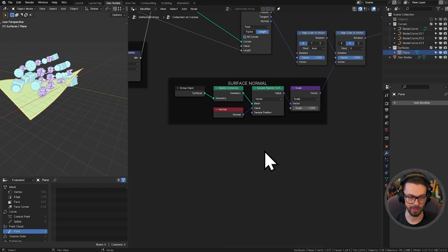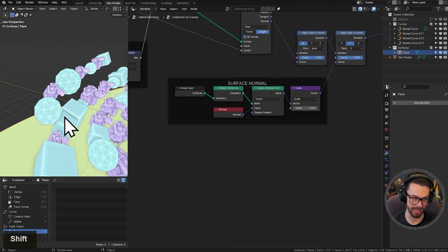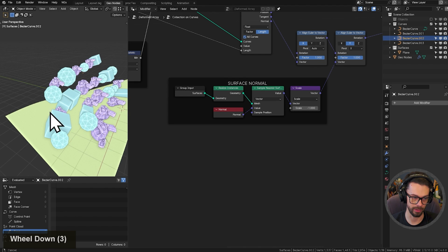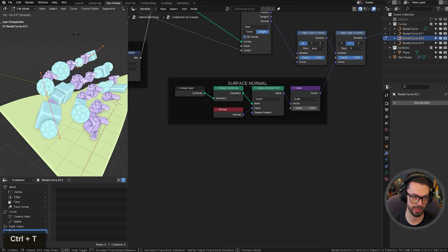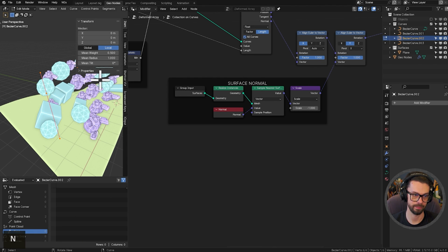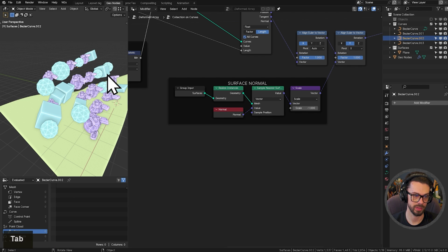Let's come back in here. We're going to be now sampling tilt. So that's the next thing that we want to do. Right now, if I take this and I rotate it, nothing happens. So if I set my mean tilt, this is under the item tab of the N panel, the information panel. In the 3D viewport, you can set your tilt in edit mode. I'm going to just set this to 90. So when we have this working, we will expect Suzanne to be looking forwards or backwards, either or. She should just not line up with everyone else.